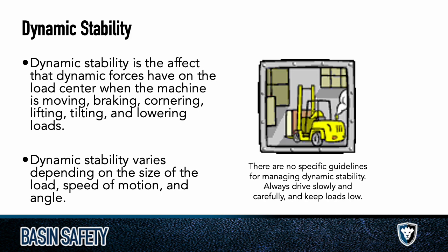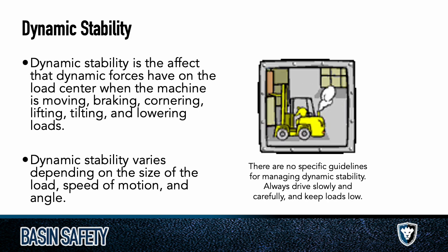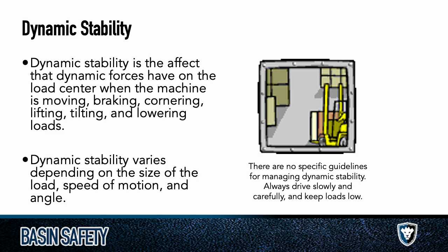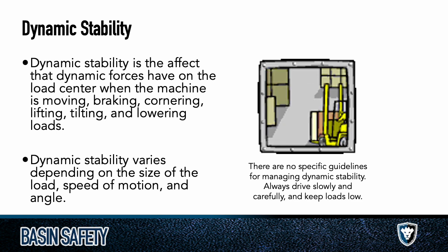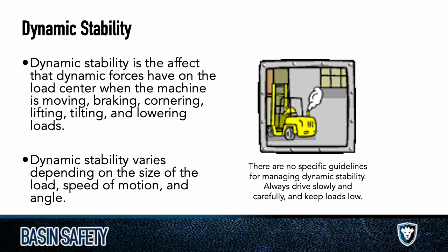When you go to move, that is considered your dynamic stability. So your dynamic stability, along with the lateral and the longitudinal stability, all come into play. As you're moving the load, your center of gravity is going to shift with your inertia. And as you make quick turns or maneuver, it's going to shift. And if the load's center of gravity shifts against your vehicle center of gravity and is overcome, it'll tip over.